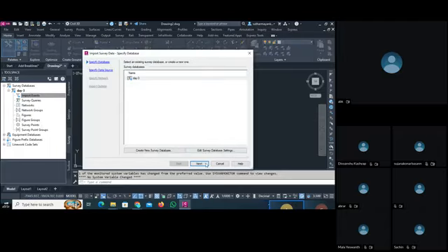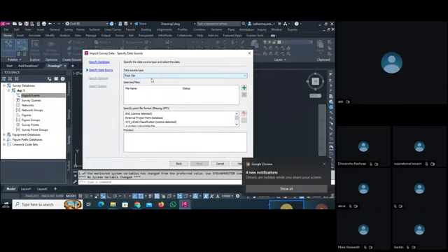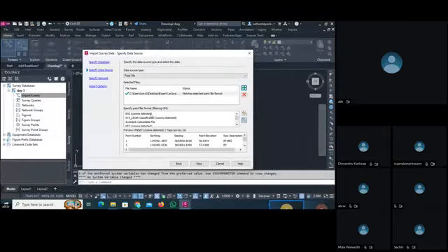Keep it as day 3. Next, the data source type we select as a point file. Then we add our point topo survey, open, set our file format as PNEZD comma delimited, and check our preview.